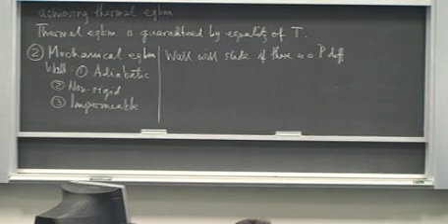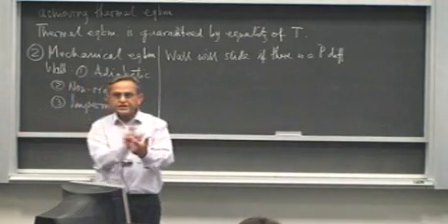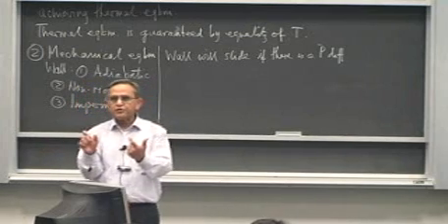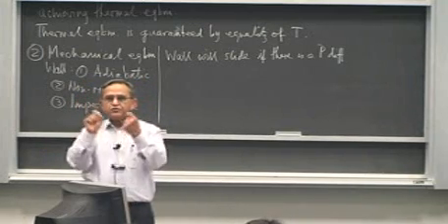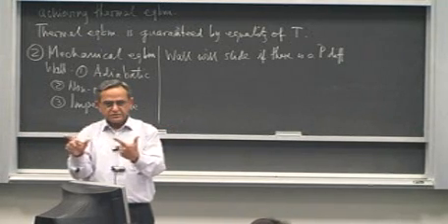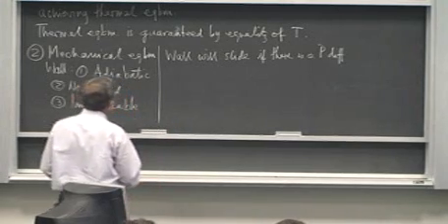So the wall will slide only if there is a pressure difference on the two sides of the wall, and the pressure and the slide of the wall will try to change the volumes on the two sides, and that change in volume will be towards equating the pressures on the two sides. So the sliding of the wall will be towards equating the pressures.